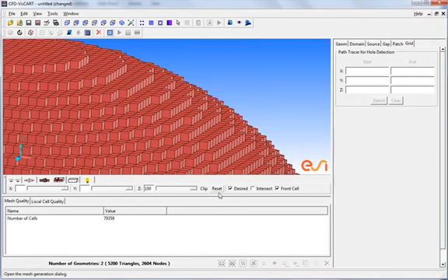Although stair-step meshes involve jagged boundaries, they are of very high quality, and as mentioned earlier, they can be used during preliminary analysis, or for studies where the physics near the walls are not very important. Next, let us try generating a projected single-domain mesh, in which the curvatures of the geometry surfaces are captured and no jaggedness exists.